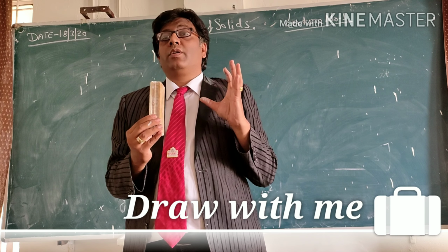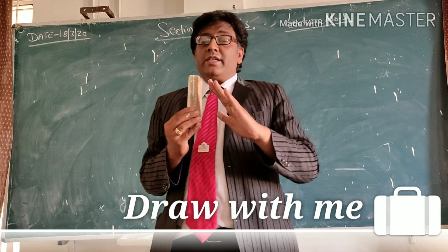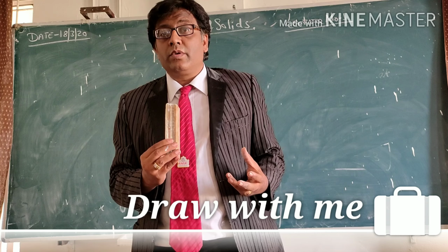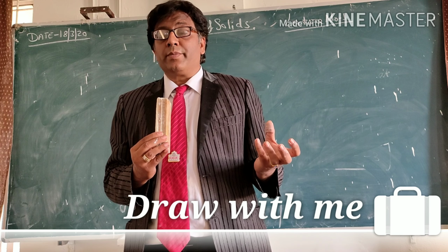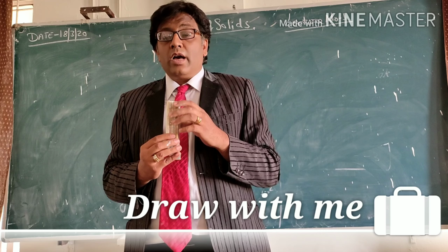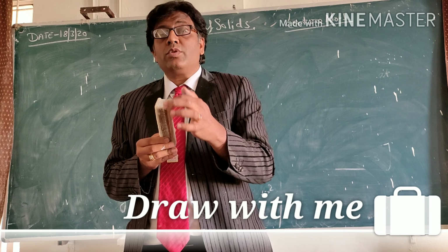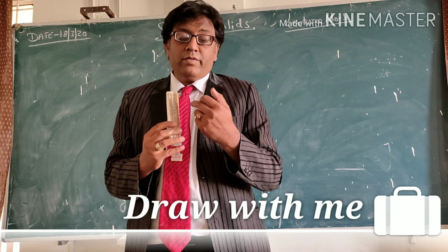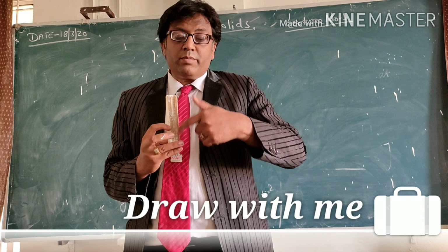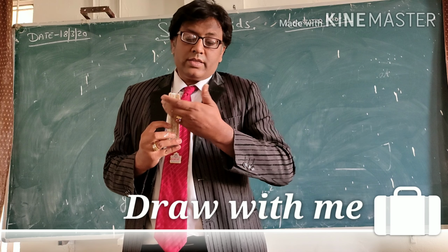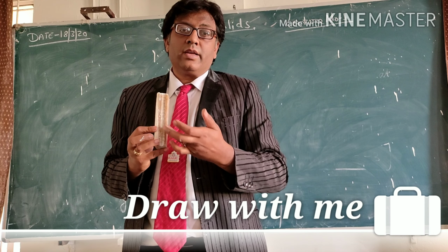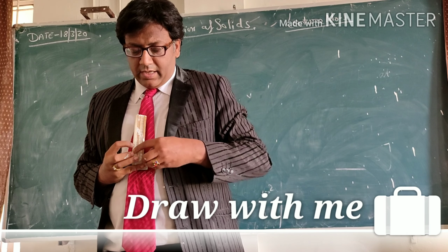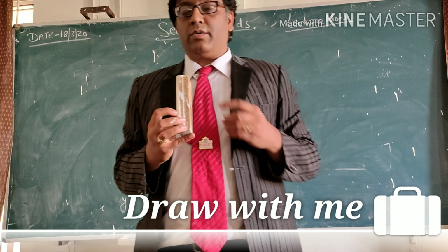sectional plane shape. Now imagine we cut this by a cutting plane and remove this part. What can we see in the top view? After removing this part, we are only able to see a square, the same as this base. And in the front view there is this type of shape, because it is inclined, it cuts like this. This is our remaining portion, the truncated part.